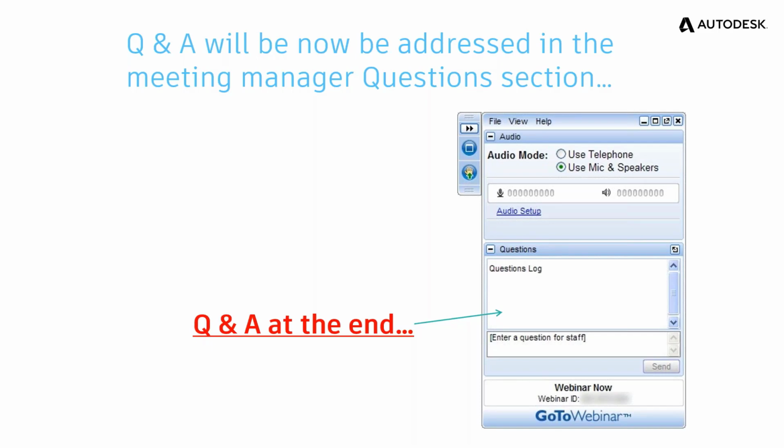Does annotative text work in dynamic blocks? Well, the block itself can be annotative. So if you're having the block adjust based on an annotative scaling, then the text within it would adjust accordingly. If you're asking if it can be adjusted separate and the block be static, ooh, that's a good one I'd have to test.